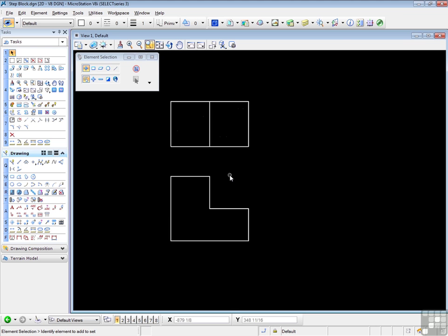We need to draw the right side view, which means we need to transfer information from both the front and the top view down to the right side view. But we won't be using the diagonal 45-degree line to do so. What we are going to do is attach a saved view of the top view and use that for the information transfer. Now first you need to make a saved view of the top.